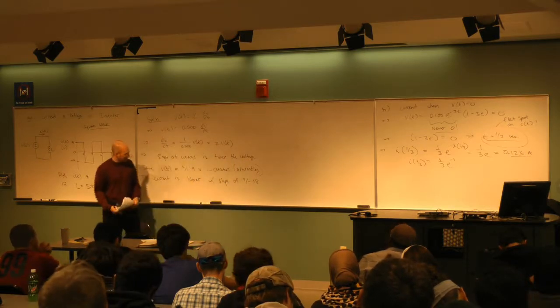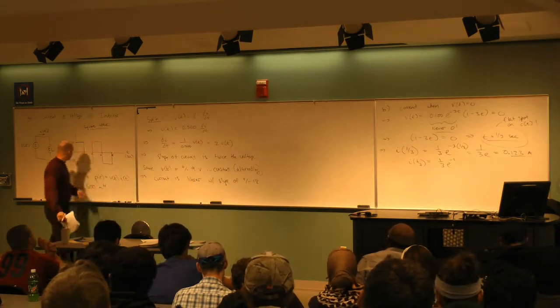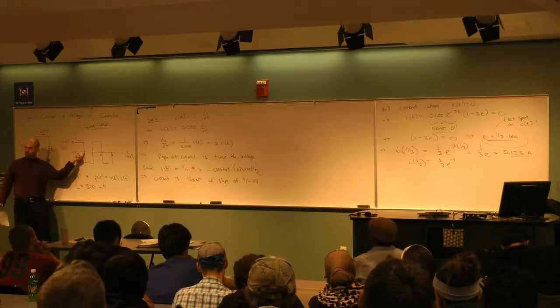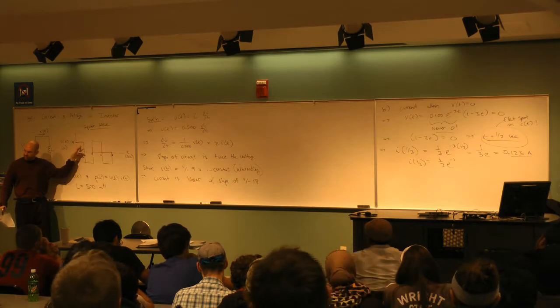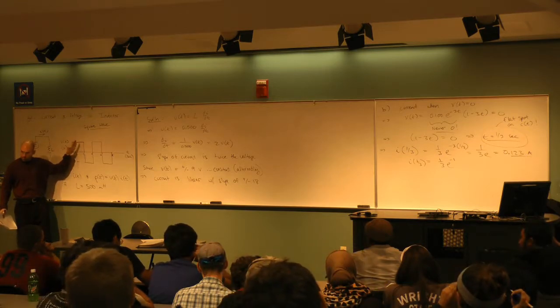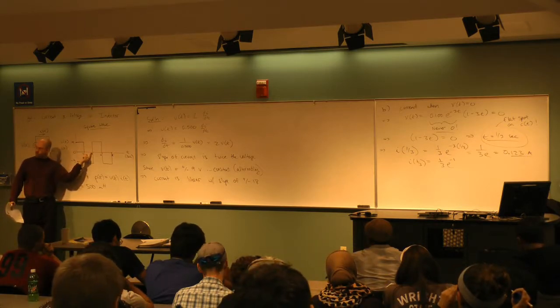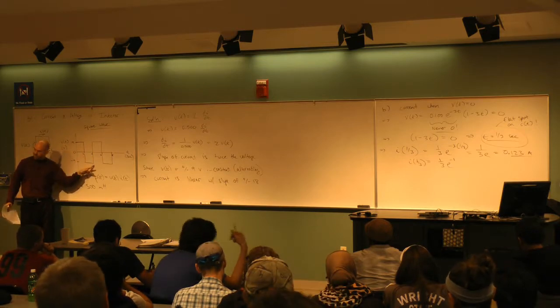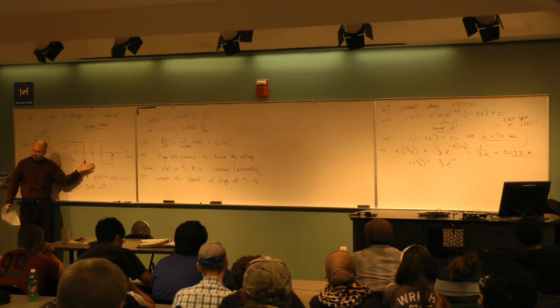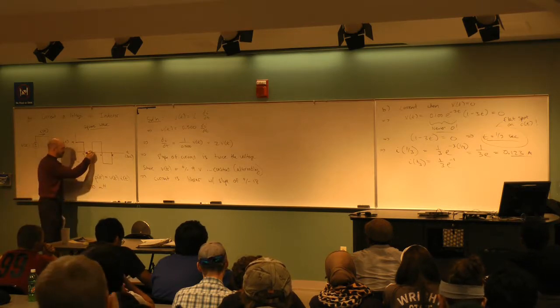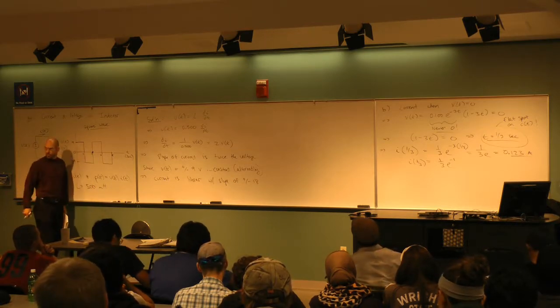Right? Does it bother anybody that I'm doing both intervals at once? All right, we can look at the first interval, and it's just the pluses. So voltage is 9. It's a constant. That means I is linear with a slope of plus 18. Second interval, V is minus 9, a constant. I is linear with a slope of minus 18.